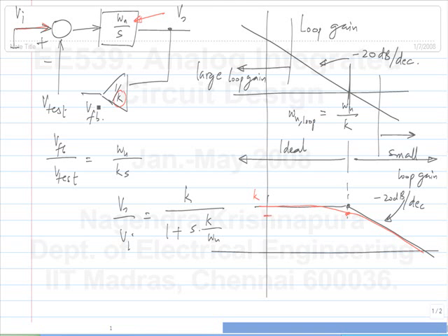This is a system with a single pole at the origin. That's it. But you can have additional poles and additional zeros also. Generally you will have at least one additional pole. So those are the main non-idealities. Ideally this is a system with the pole at the origin. Now non-infinite DC gain also means that the pole is shifted away from the origin, right? So the pole will not be exactly at the origin, and also that will not be the only pole. There can be other poles.